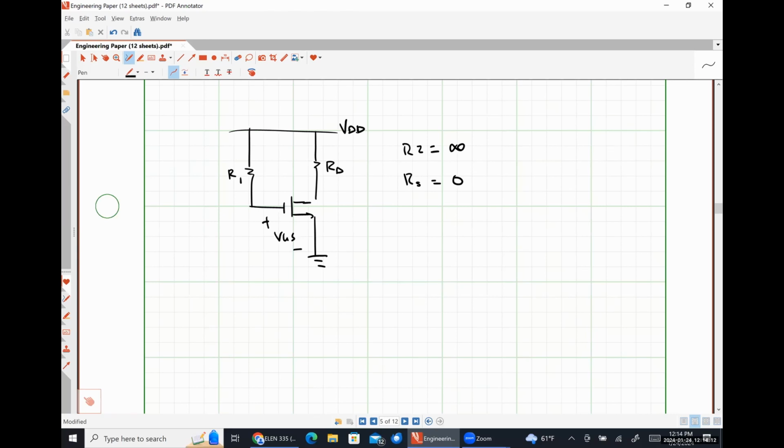Technically, it depends on what our threshold voltage is and what our supply voltage is, but I can say pretty definitively here that the overwhelming majority of combinations of supply voltages and all that kind of stuff are going to wind up forcing you into triode here, unless RD is just very small so that there's not an appreciable voltage drop. But finding VGS is pretty straightforward for this.